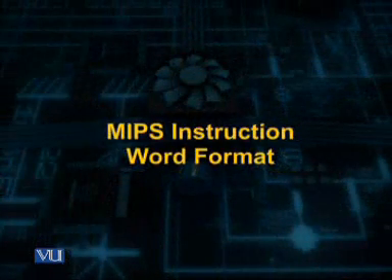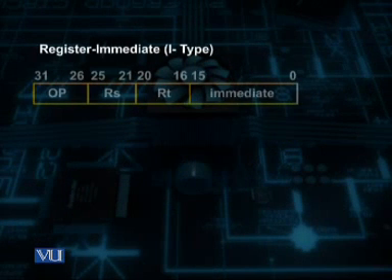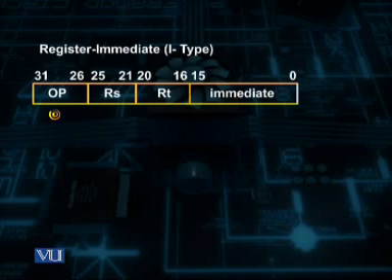As you can see from here, these 4 fields, again reading them from left to right, are the fields for the operation code, the field for RS, the field for RT, and then a 16-bit field to define a 16-bit immediate value. Here, note down one difference as compared to the register type instruction word. The difference over here is in the field RT.